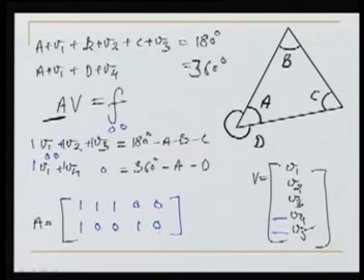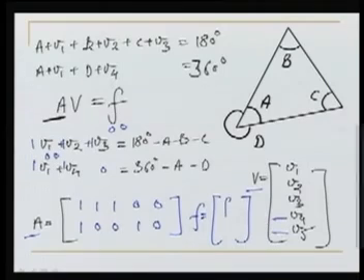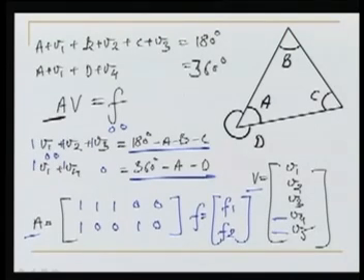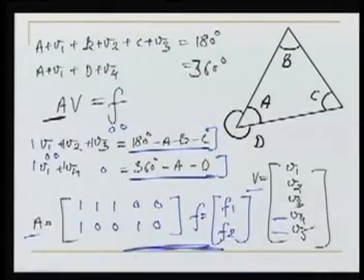That is A. So this is A, V, and what is F? We can say F1 and F2, where F1 is this term and F2 is this term. So this is a constant here, this is another constant, so this is F1 and F2. So what we know now, at this stage, we know A, we know F, and in our method of condition equations, if we know A and F, we can find K. Once we find the K, we can also find the V, and once we have found the V, we can find our parameters. Okay, so the important thing was forming these basic matrices, then rest is simple matrix manipulation.